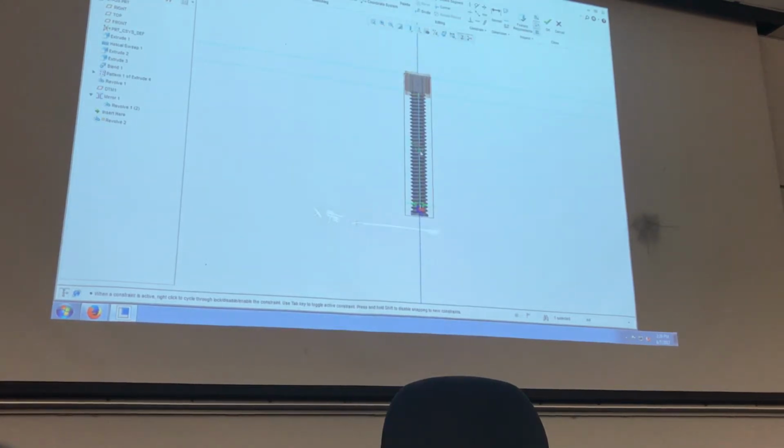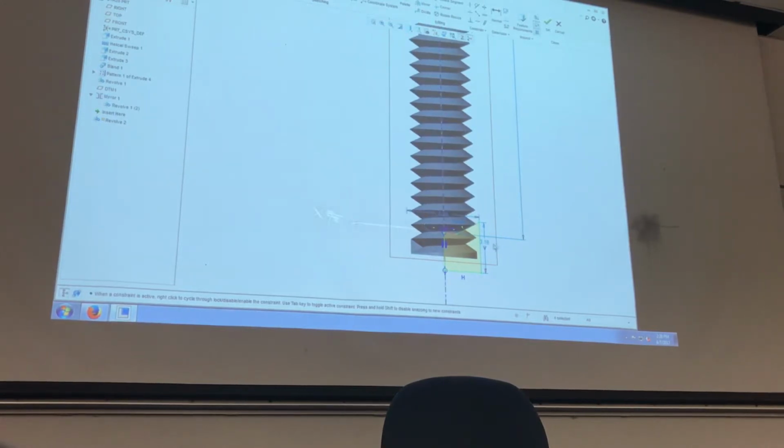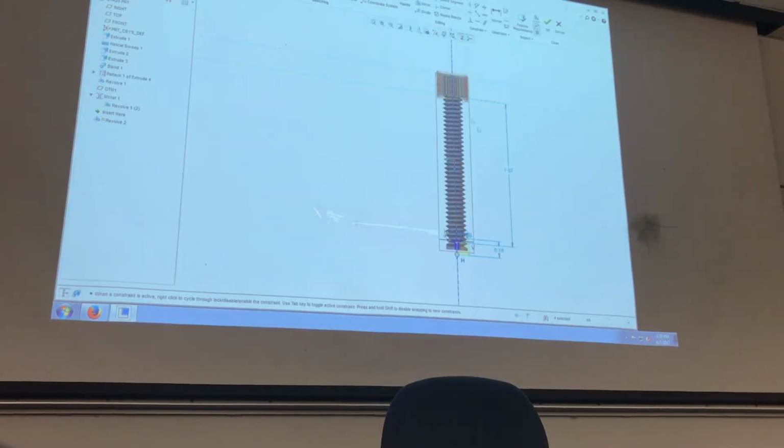And that dimension looks like it's coming off of here, which is fine. Okay. From there, take another line. From that point, come off at an angle, go outside the part, come down, over, and up. Okay. So now I've got this dimension here. I've got the dimension from the bottom of the head here. So this dimension will determine the overall length.